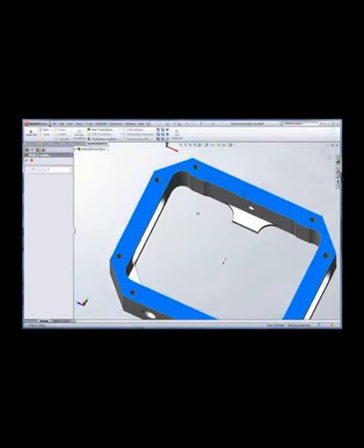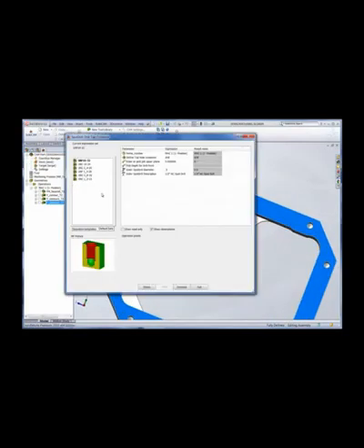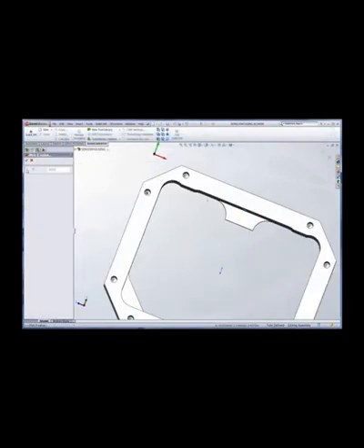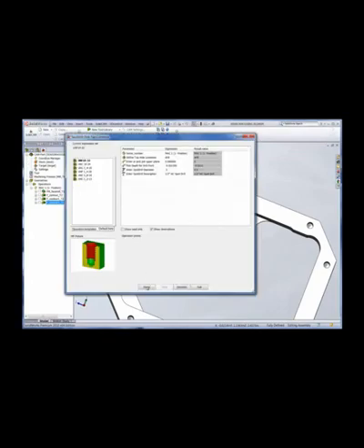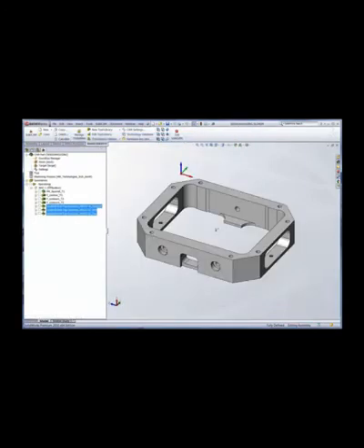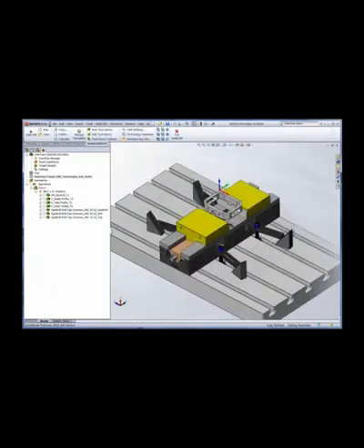Hole processing can be quickly and easily accomplished using machining processes. We'll take a spot drill and tap hole process. In this case, they're 10-32 UNF holes. Notice there's only a few parameters to assign, one being the definition of the geometry. We'll simply select the top plate and pick up all the holes.